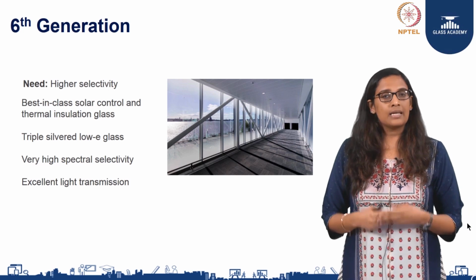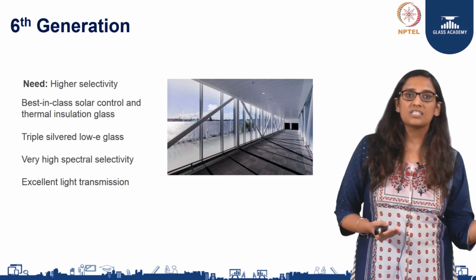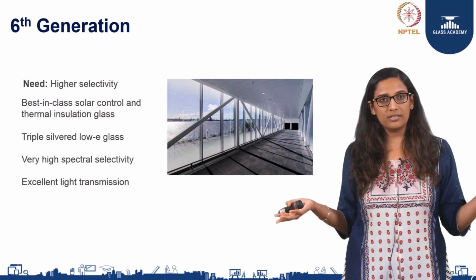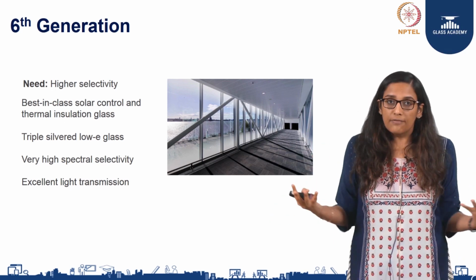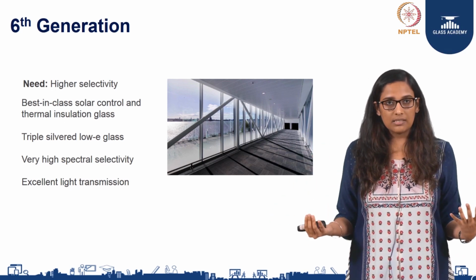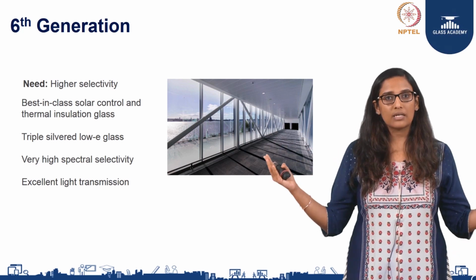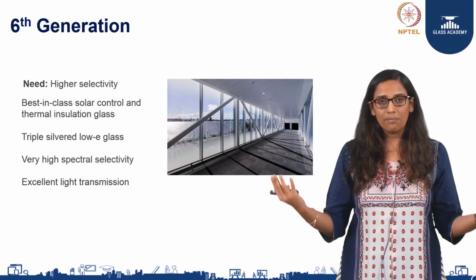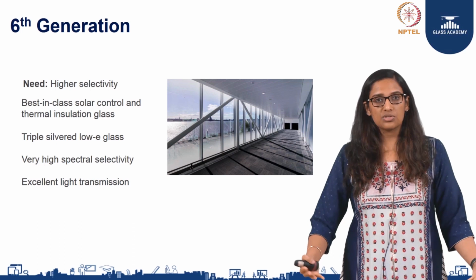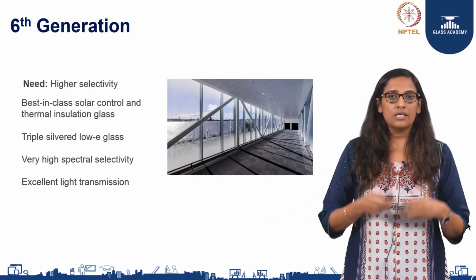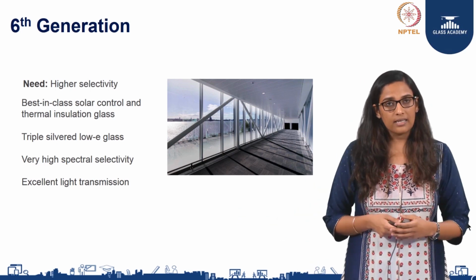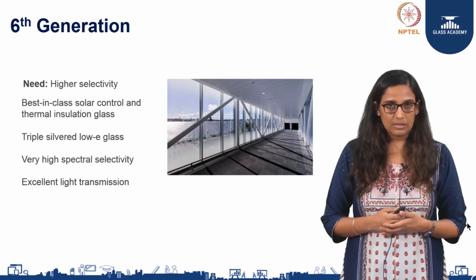This glass can give you up to 70% light transmission and up to 0.3 solar factor, therefore changing the way that you would design facades, therefore allowing you to design more glazing and wider openings, giving you access to the outside world, bringing in more natural light so that the occupants of your building enjoy the best possible comfortable situations.